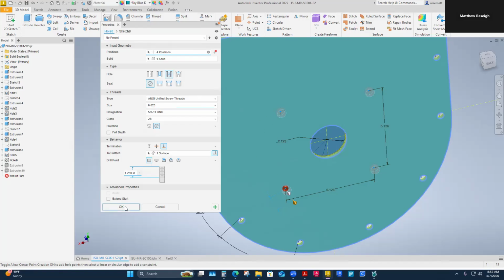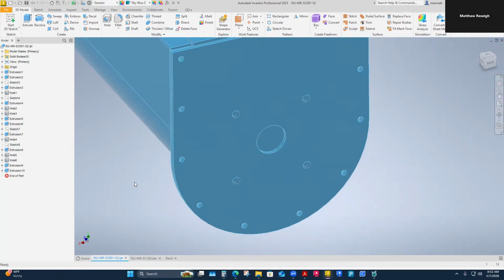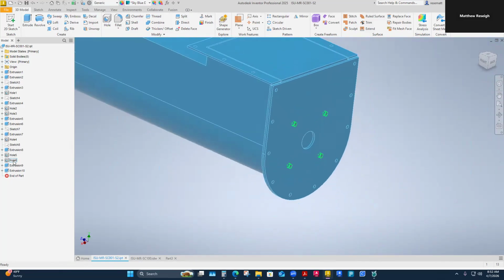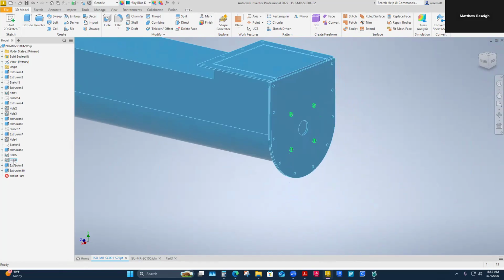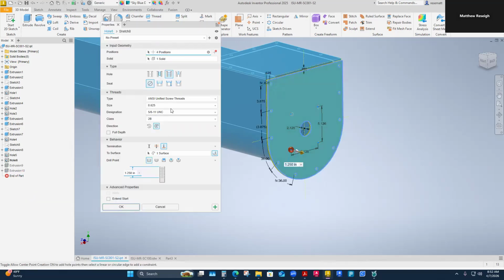This is changing the solid. I'm going to say okay. It's a pretty big bolt, but I think I'll put that in. It was my hole on my solid, on the inlet end of this screw conveyor. It's just because I'm looking at the resource material for the bearing and analyzing it, saying if I put a 1/2 inch bolt in there, I could put in... I made it 5/8. I had a 1/2 inch originally, and all I did was change it to 0.625, and that created a 5/8-11 thread in there.